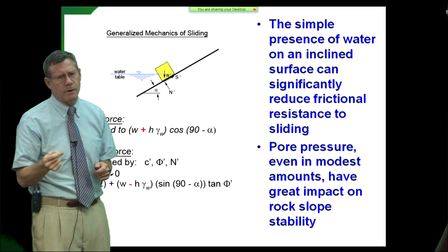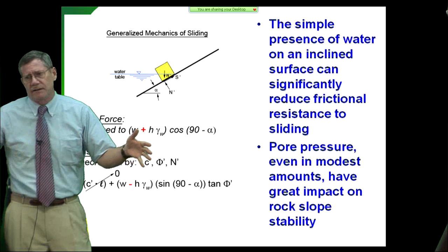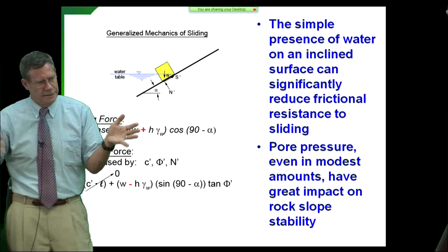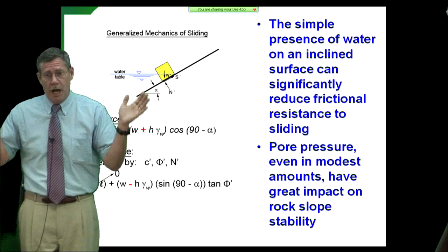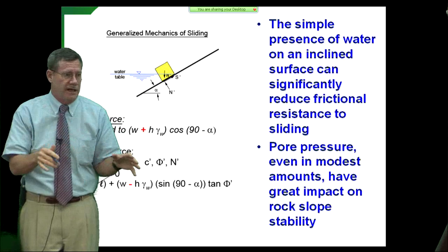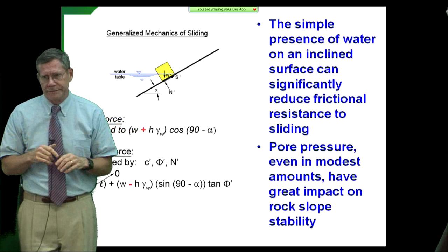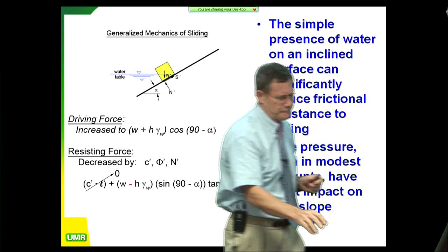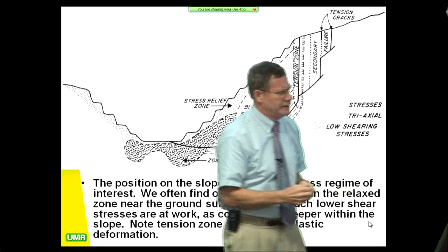The reason we limit it to 12 inches a day is so we can evaluate the seepage around the dam and make sure we don't have a big conduit. That's what happened at Teton. And this conduit showed up at 7 o'clock in the morning, and by noon the thing was gone. And they had equipment out there, they had contractors out there, they were just finishing the dam, they tried everything they could do, and nothing worked. Same thing happened at Baldwin Hills in 1963 in Los Angeles. And at Fontanelle on the Green River in 1965.